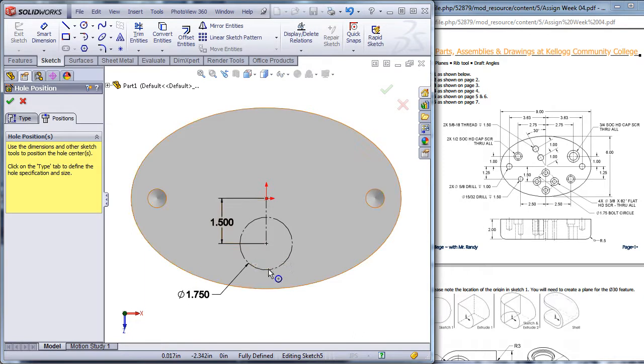You can get away with not turning them into center line, construction line, but I want you to do that. I will pick on you if you don't. So don't leave these solid object type lines. I want them to be construction line geometry. Now I'm going to go back to the point tool, and I'm just going to drop a point on each quadrant point of that circle.